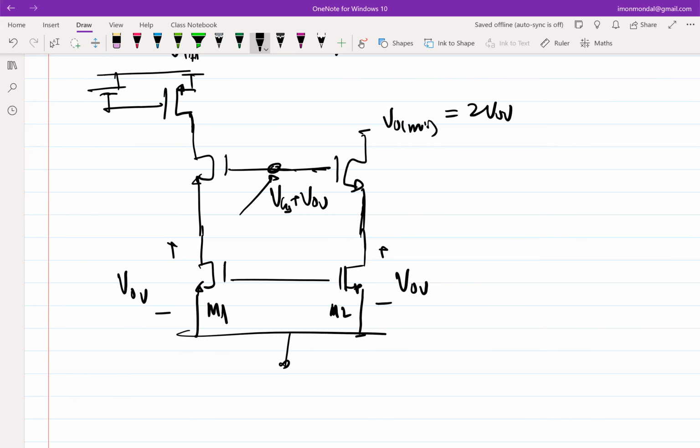You are just throwing terms. What is going to go below threshold? Why? Because VGS is constant, right? VSG of the PMOS is constant. So the drain voltage of this PMOS will increase. Because if we assume that this is floating, it can be anything, but let's assume that it is zero.